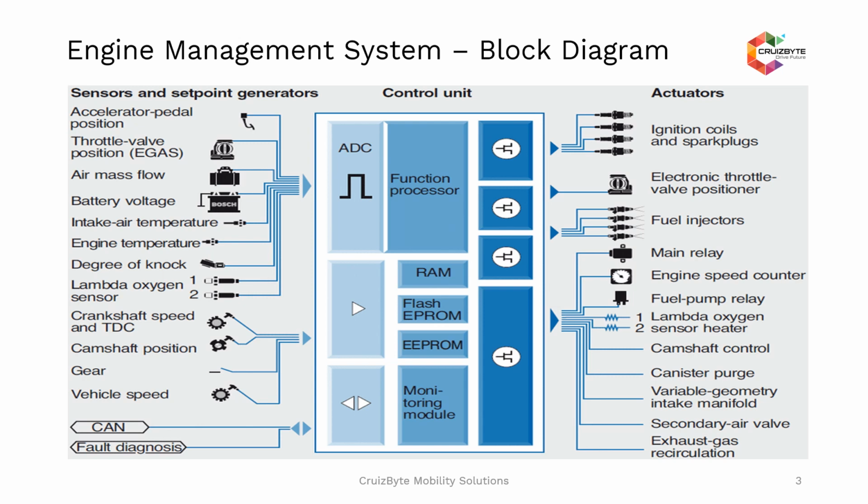So the idea of this particular Input Output Control by Identifier SID is to substitute a value for the sensor, or take momentary control of the actuators directly from the tester by providing the SID along with some parameter values.